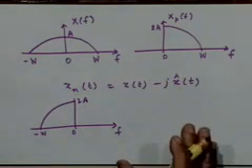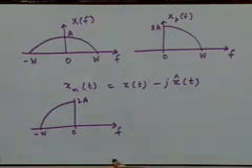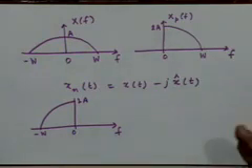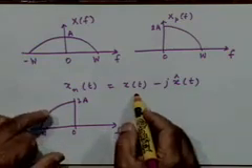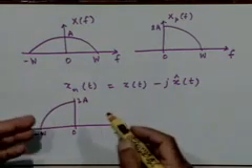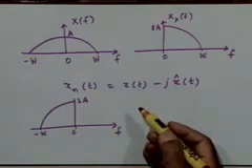So you see a direct analogy between what we are doing here and what we are already used to when we try to represent a sinusoid as a real part of a complex exponential. Here also, the signal of interest, which is a real signal, is the real part of either x_p(t) or x_n(t). The same relationship holds. So the development is absolutely parallel to what you already use very frequently in the context of sinusoids. Only thing is, now you can use it in the context of an arbitrary signal.